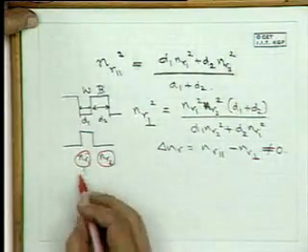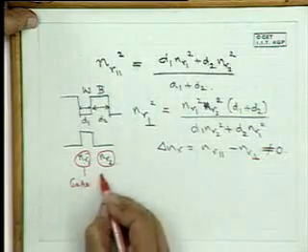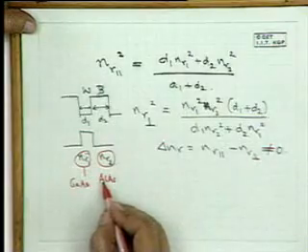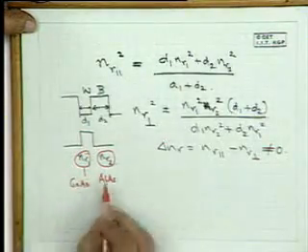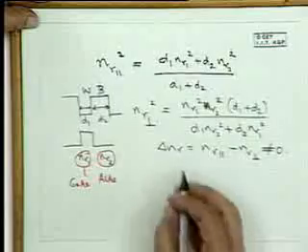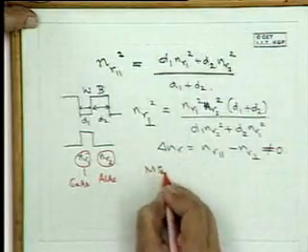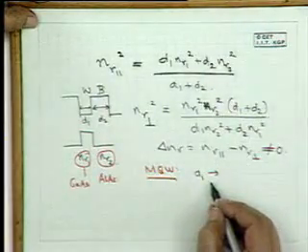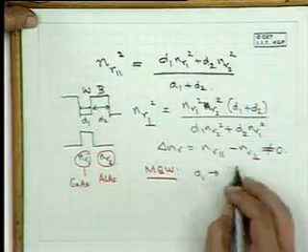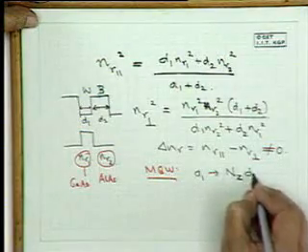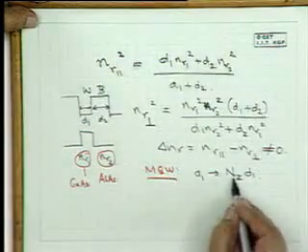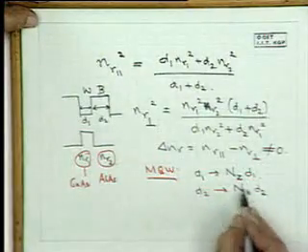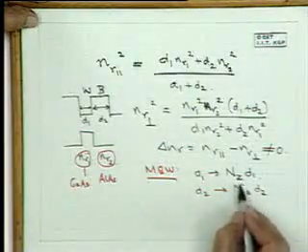Why? Because typically this is say GaAs, and for quantum well you can make this, where the optics are concerned, aluminum arsenide. You don't have to go for gallium aluminum arsenide. In order to get the maximum change in refractive index, you can make this aluminum arsenide. And for a multi-quantum well, what is D1? D1 would be NZ into D1, and that's the number of wells, and D2 is the number of barriers, NB, into D2. So you can accentuate the differences by having a large number of wells and barriers.